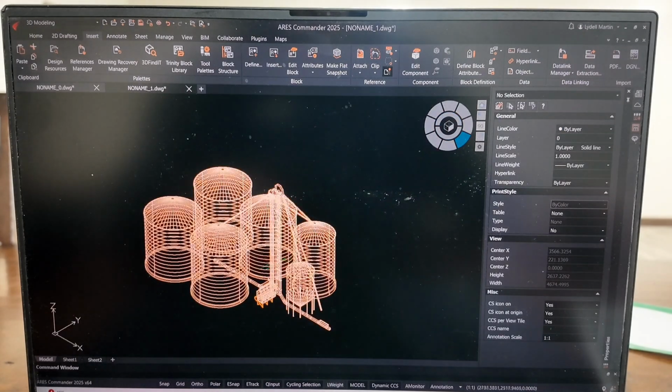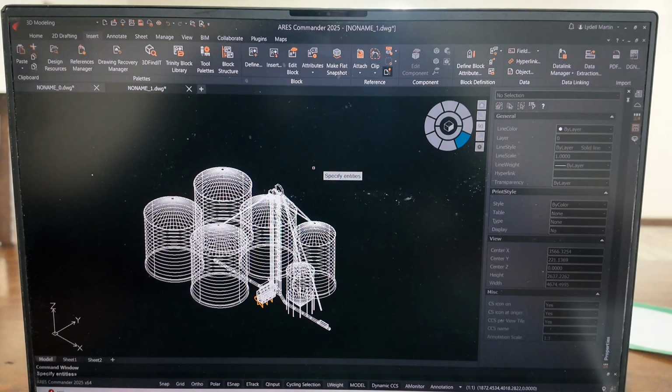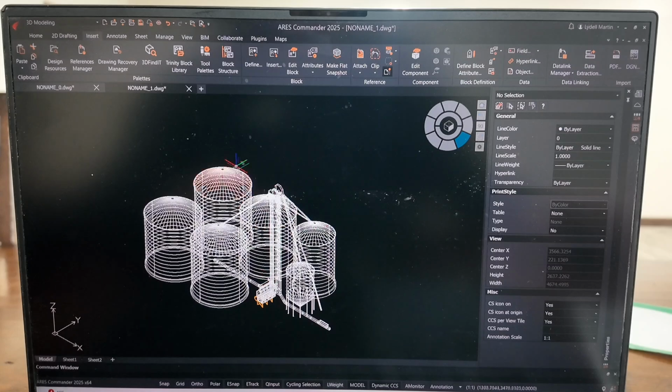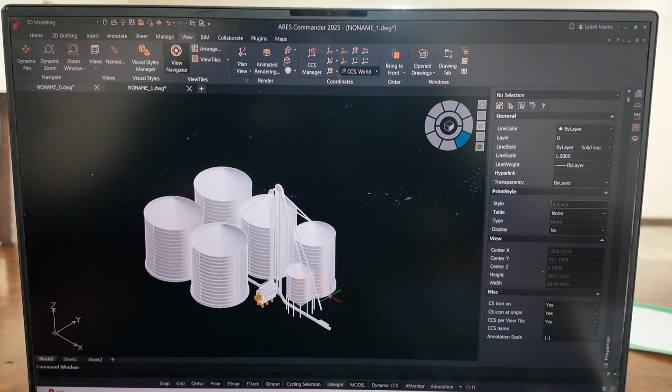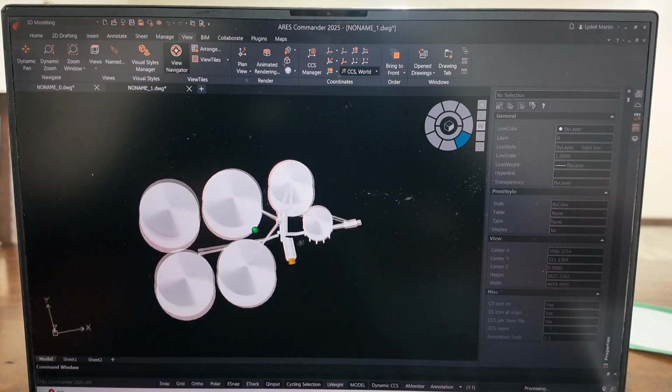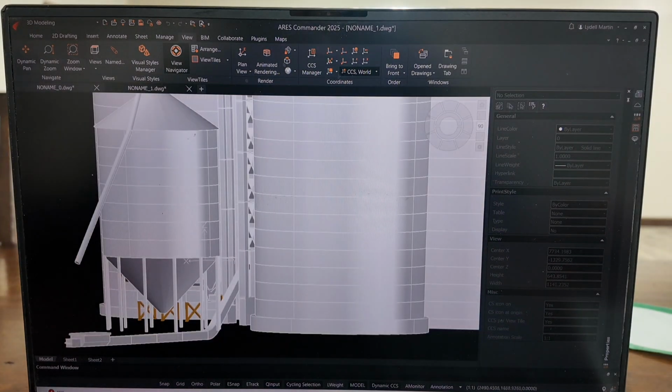In here, I have everything drawn, but if we said we need another drag conveyor in here. Now, when we open this file, it's like one block. So what we're going to do is type in EXP, and then select explode. Then we're going to left click and right click, and it blew it apart. Now we go up to the top, we hit view, we hit gray with edges and orbit, and now we can roll this thing around and see how it looks from every which direction.